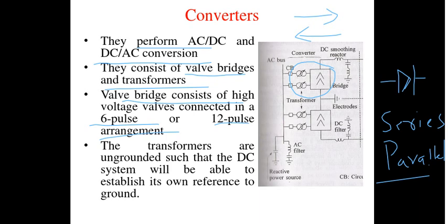And apart from that, you may have very sophisticated auxiliary systems also here. So gate control logic, right? Whenever you have the parallel or series combination of the SCRs, how exactly are all the devices required to be triggered simultaneously, and how is it achieved? Then the cooling systems, the snubber circuits, the temperature measurement, so many measuring components, all those things will become a part of this converter system. So that all completely decides how exactly your converter system should look.